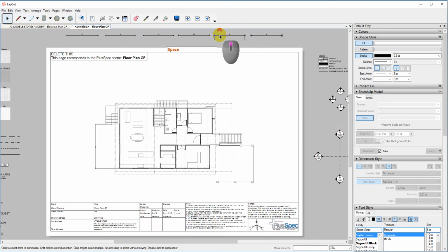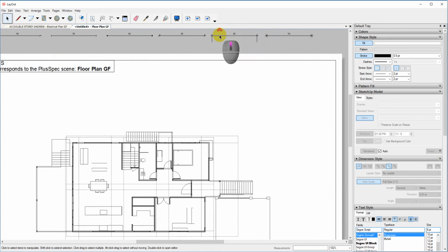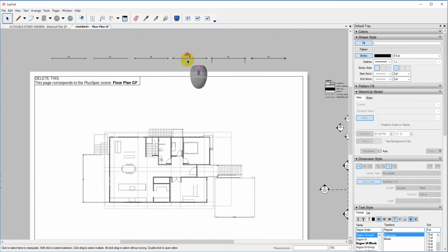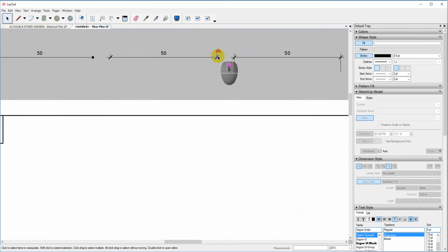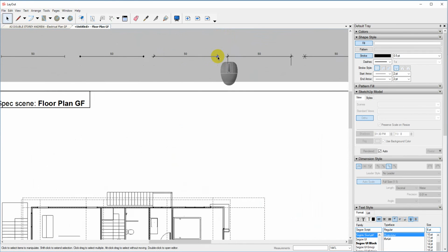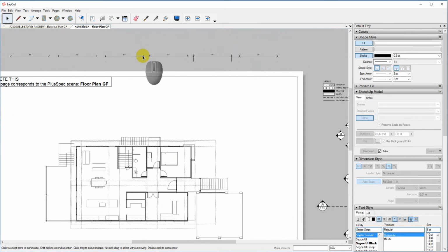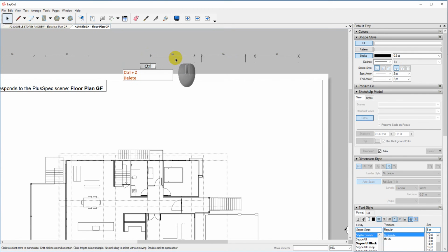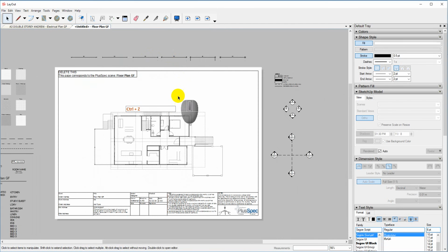Okay, so this particular dimension style here will actually run a leader all the way from the geometry with a slight gap to show you where that goes. And this particular one here, you can notice there's no leader, however just a line and across. You can have dots, and if you don't use any of these, just go through and delete them. Simply delete and then save your template. Okay, I'm going to undo that and leave it there.